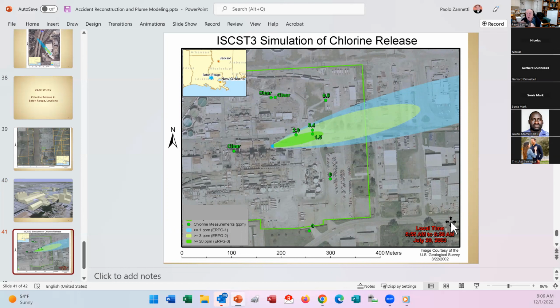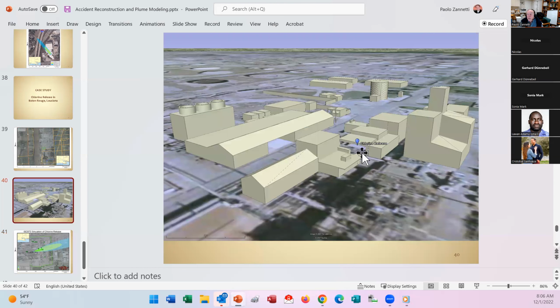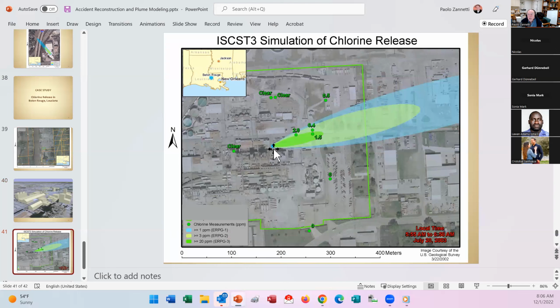So they cannot tell you, oh, you are working for the defense, so you are trying to minimize air pollution. They could have said that. Oh, yeah, you chose CFD because you wanted to have a lot of horizontal and vertical diffusion and spread the plume to have lower concentration. They could have said that. So I felt comfortable using a Gaussian plume model, which of course can be done with a lower budget than a CFD.